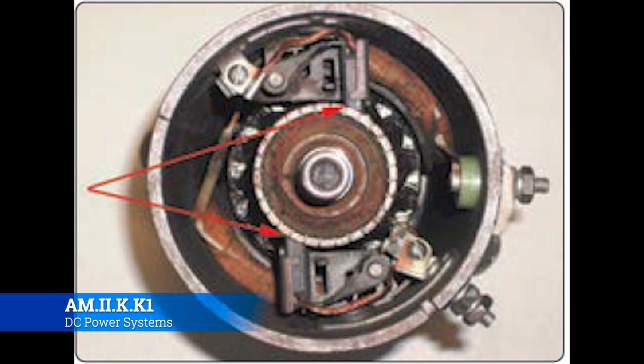You also want to look at the electrical connections. Make sure they're not frayed, they're not corroded, they don't just break off in your hand whenever you come off. And that's most of the time. You're going to have either one or two power leads that go to it. Sometimes, depending on the model, you might have one lead that comes off of every phase.